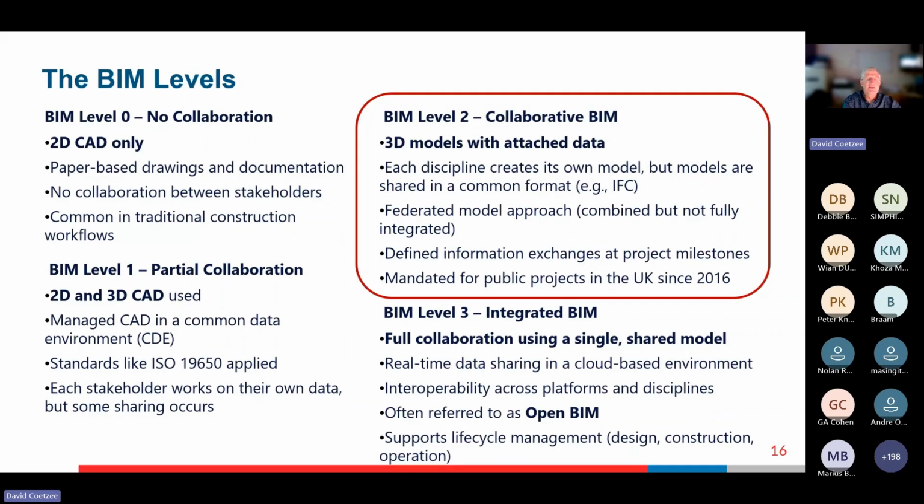Now as we get to the end of that project, clash detection becomes less and less important because the design development phase is finished. We're in the construction phase. At completion and at various intermediate points, we do point cloud scans and then check that against our models to see whether we've met our tolerance requirements and everything is in the place it was intended to be.